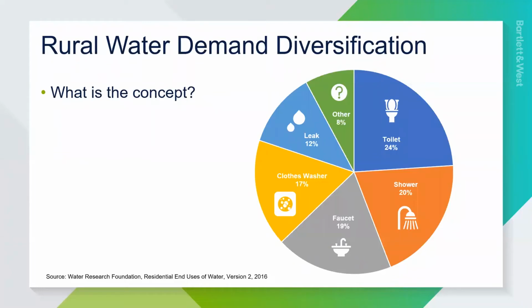To help explain that with an example, think of a water system where you have maybe 20 customers on a distribution pipeline. And say the peak demand of those customers is 5 gallons a minute. Well, when we design and model these water systems, it is not 5 gallons a minute times 20 to give you a total instantaneous peak demand of 100. It's much lower than that. And that is due to the low probability that every one of those customers is going to be pulling peak flow at exactly the same time.